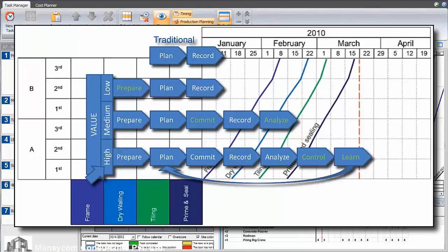We also use pull planning processes to implement realistic look-ahead plans and achieve commitment to the plan. Analysis of actual productivity data provides us forecasting and warnings of any potential clashes in the field, and we use these forecasts and the alarms to inform site meetings, implement mitigation measures, and really control the plan. We then complete that learning loop to provide better starting data and improve our next plan.